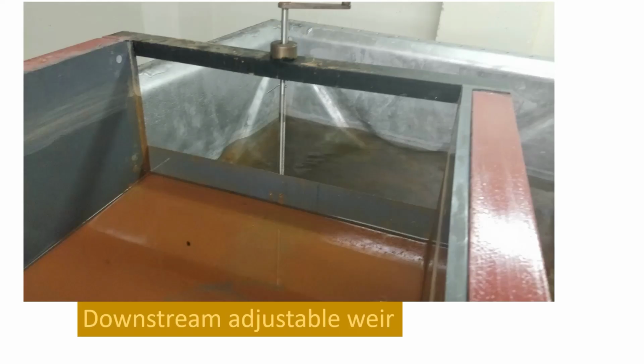The downstream end is an adjustable weir, so we can just raise this weir up and down to get a different height, change the height of the downstream end so it changes the height and position of the hydraulic jump.